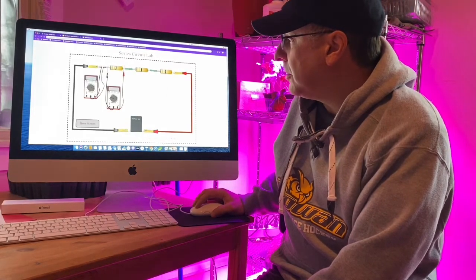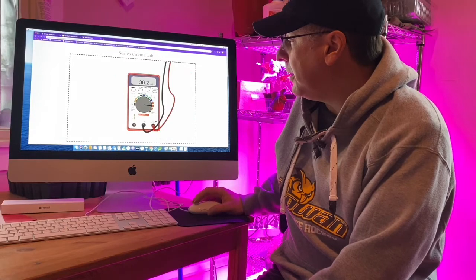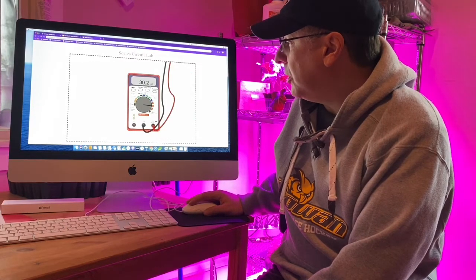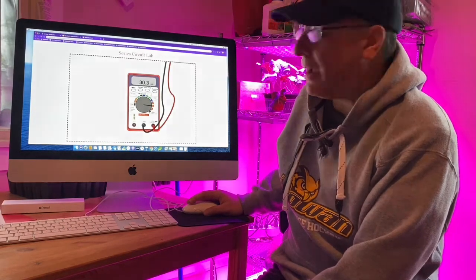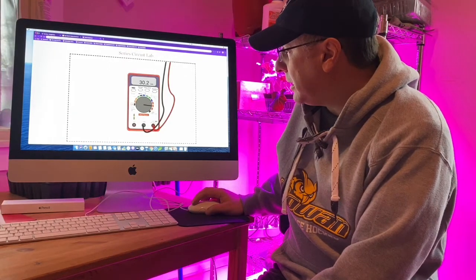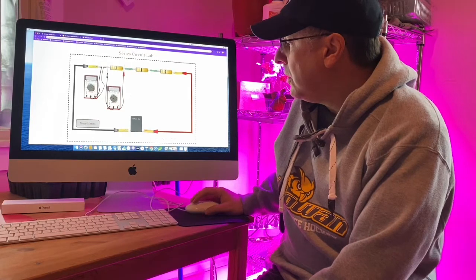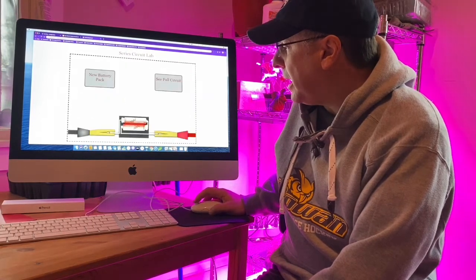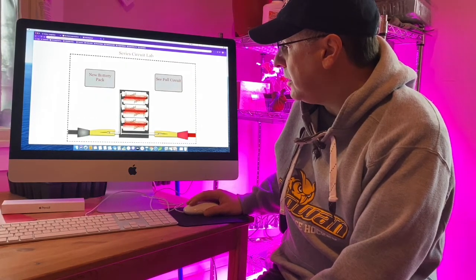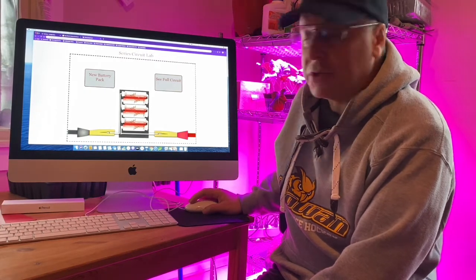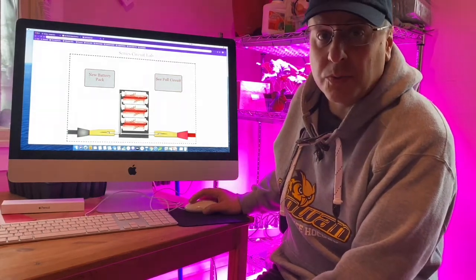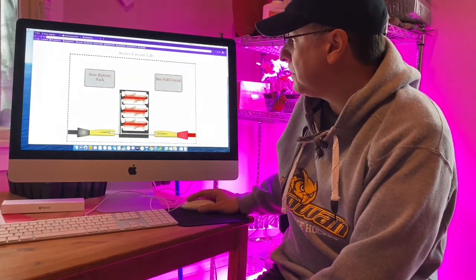Okay, this meter will give you your current, and again it will jump around. Try and get your average value. Again, it's set to milliamps, so make sure you are aware of that. Okay, you have a battery box at the bottom. With that, you can change the number of batteries inside. Remember, these are AA batteries, so each one is 1.5 volts.